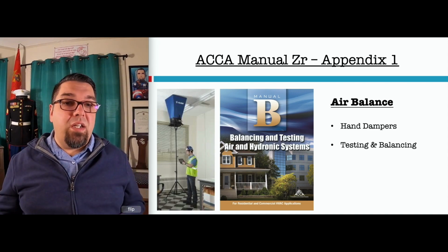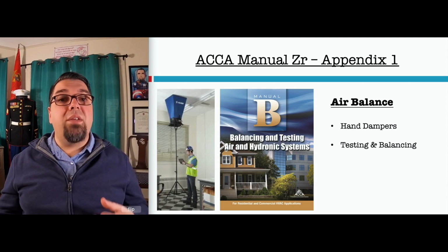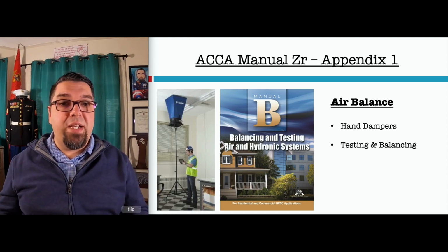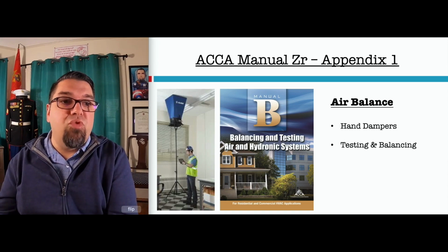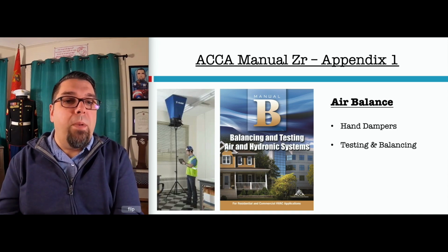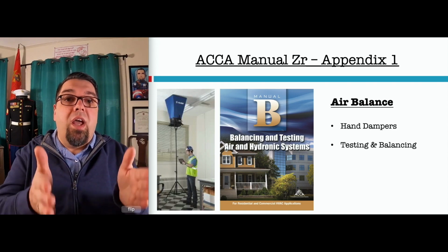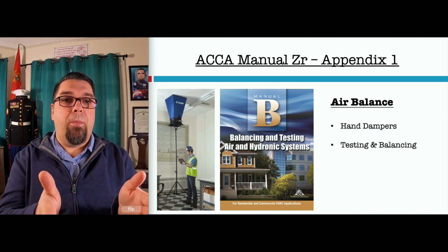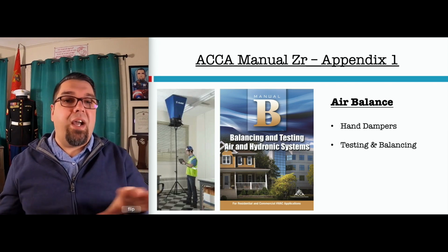Testing and balancing is part of the commissioning process. Make sure you're finding a way to measure the volume of air delivered to the space, and you're within, let's say, 10% of what the design is for that space. That's really, really important to follow up and make sure you commission the entire system, not just getting the airflow and refrigerant charge right on an air conditioner or heat pump, right? You also have to deliver it to the space, and this completes that commissioning process.